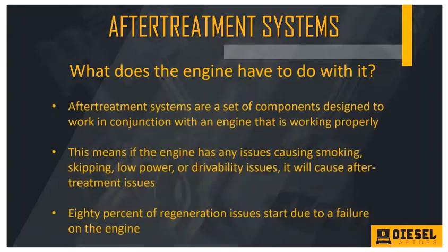So what does the engine have to do with it, right? Because today we're talking about after-treatment systems. What does the engine have to do with it? The engine has everything to do with it. One of the things that I really want to stress is when we have trucks come in with regeneration issues, what happens with a lot of technicians, and not all, but a lot of them, they almost get tunnel vision. I'm guilty of this earlier in my career as well: you see a regeneration fault, and you automatically assume that something's wrong with the regeneration system. And when you think of the regeneration system, you're thinking of the DOC, the DPF, if it's 2010 plus, the SCR catalyst, and then all the sensors that coincide with that.